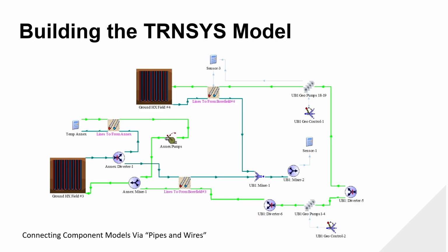Okay. And then again, how does each building interact with the loop and share energy in those shoulder seasons? If you have a heavy cooling-dominant building, showing how all that works together. And then of course, with your geothermal systems, showing, again, how you dispatch that, the long-term net effects. The great thing about this program is I can actually separate all those bore fields, where all the other programs generally put the bores into one model or location, which doesn't then give you the correct output of the drift or how it impacts over the long term.